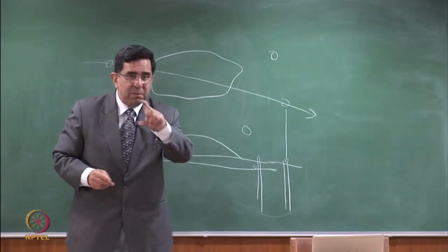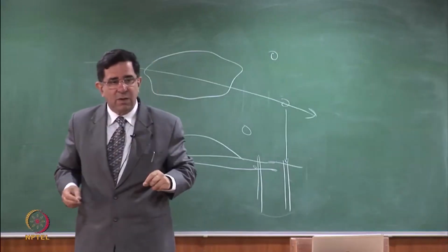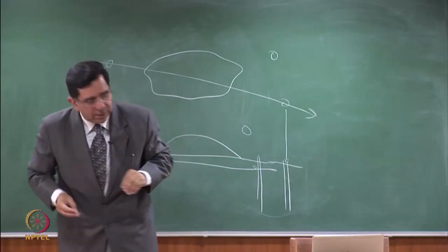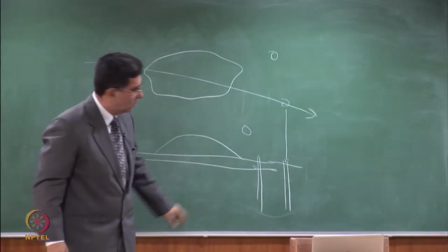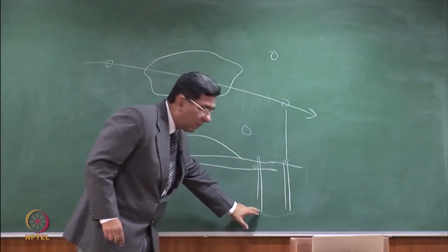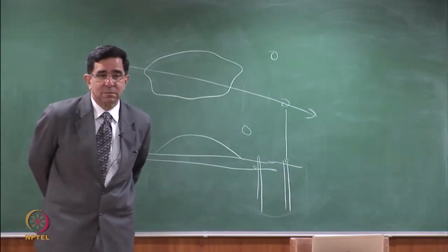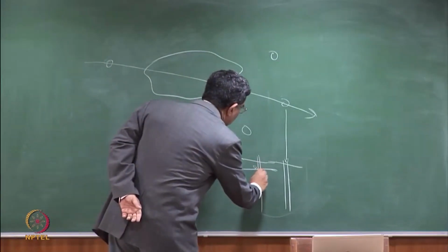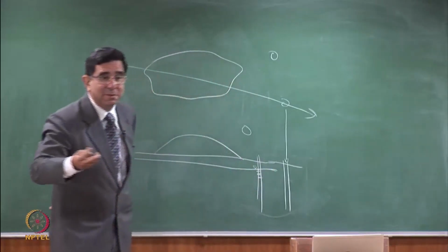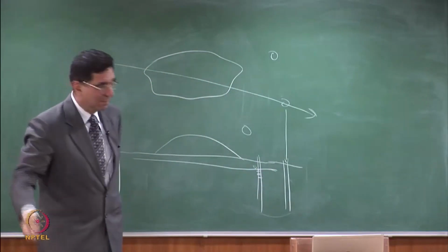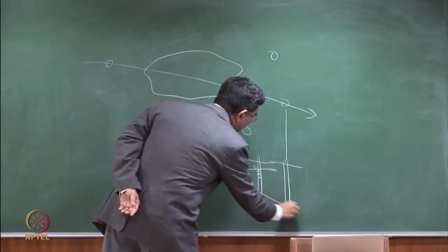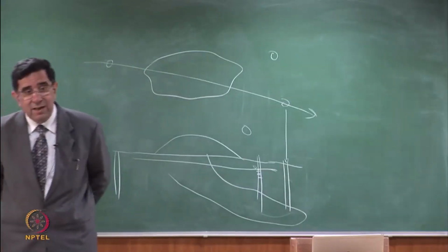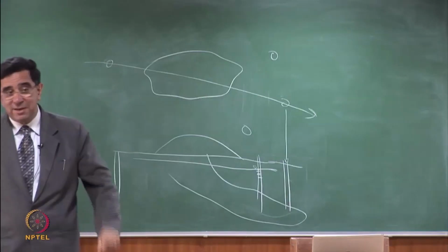I need to say where my screen will be. Why? Because then I will be collecting the groundwater from that area. So can you tell me where I should put my screen? Should I put the screen here or here or here? Maybe you will make a well in which the screen is here. You will say I will detect, because maybe the contaminant will float. You put it like this, but the contaminant is actually going like that. You will miss it. Your well will not get that contaminant unless your screen is in the way.